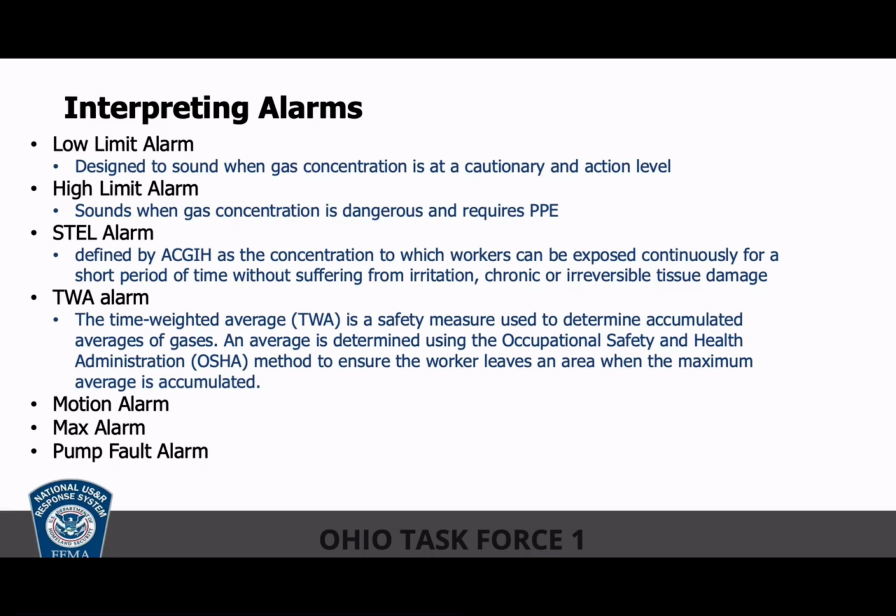So that's an important thing, because if we're in that confined space and we're downrange and we're going for the win and we're trying to make this happen, if you're not going to be the person that pays attention to that STEL alarm and actually does something about it, you're wrong. Now, here's the problem with STEL alarms. Once it's alarming in most all of our meters and their configurations, it doesn't stop alarming. You have to remove the meter from the environment, clear the alarms, turn it off, power it back up, and go. So it's hit that STEL, and it says you've got too much of an exposure.